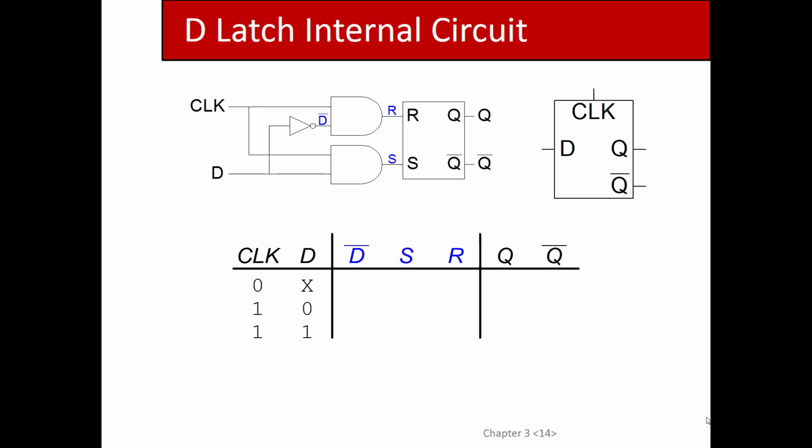Yeah, you're right. If I've got a 0 stored in my latch, and I put a 0 in as D, and maybe I hid the clock and I'm not going to show you what clock is, all I'm going to show you is that D is 0 and Q is 0. You might think that clock is high, when in fact it's not. But that's only because coincidentally my input matches the value stored internally in the latch. I think that's what you're asking, right? But that would just be a coincidence. In reality, Q is not 0 because D is 0. Q is 0 because D was 0 when I shut the clock down. When you say shut it, you mean you're changing it to 0, right?